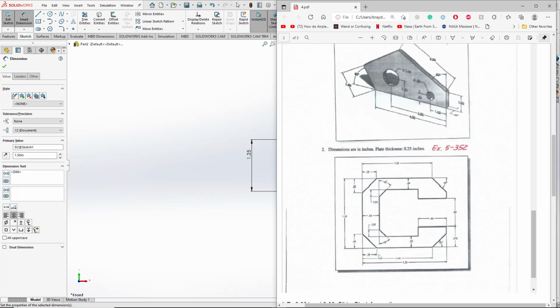External chamfer, external chamfer. These chamfers are 0.25. Really easy to add. You could do it manually, but also, there's no point. You can just add a chamfer. I'll show you that. So then we can do an internal cut as well. Just ½ inch in, and then a square with some chamfers.